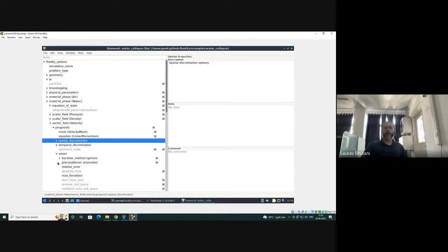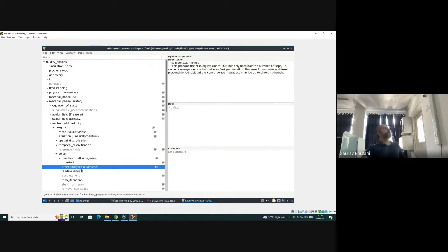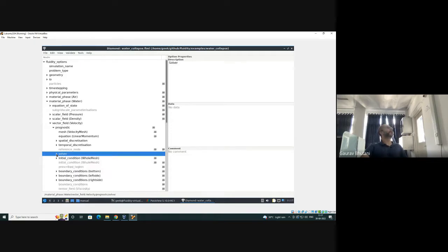Then when you have a linear system, you want to solve it using some iterative scheme. So you can choose that scheme here. You can use the minimal residual method, you can use conjugate gradient method, Richardson method and so on. There are many options available for solving linear systems. We also use preconditioners. If you have done a numerical methods course, you'll understand these ideas. But we don't need to worry too much. The default settings usually are okay. So we will not worry about that for now.